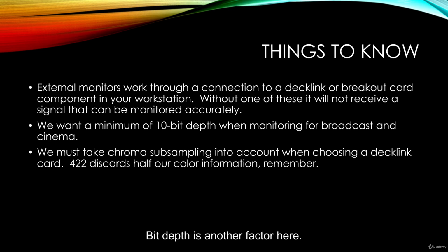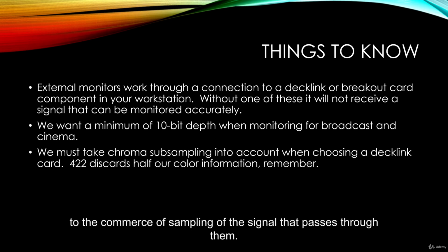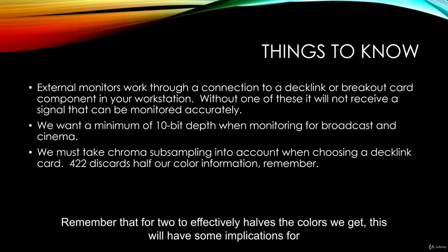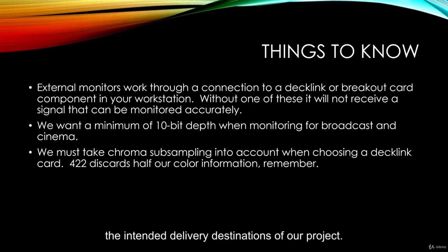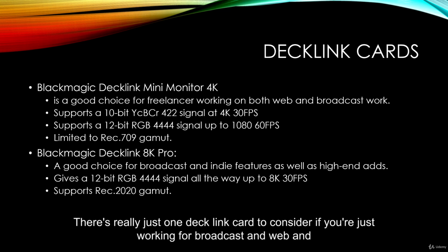Bit depth is another factor here. The majority of DeckLink cards will support 10 bits of color, but they will have different limits to the chroma subsampling of the signal that passes through them. Remember that 422 effectively halves the colors we get. This will have some implications for the intended delivery destinations of our project, so we need to keep all of this in mind.